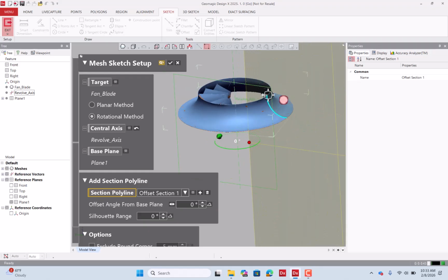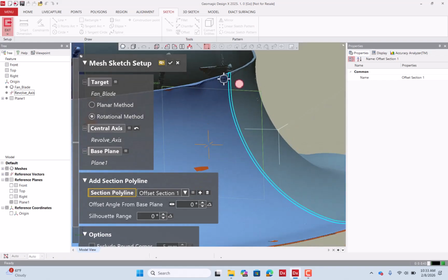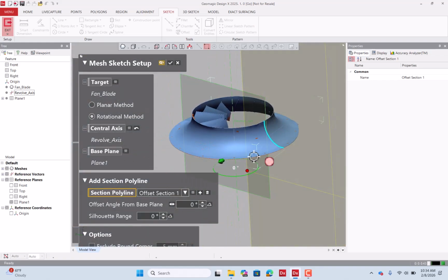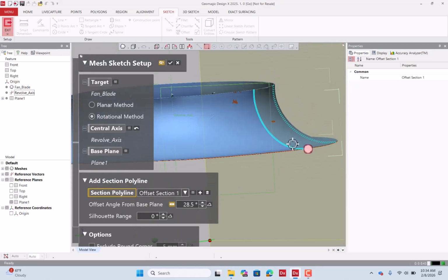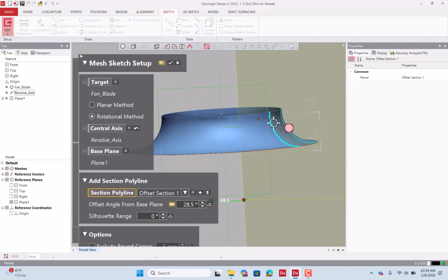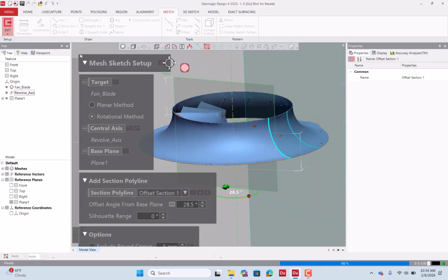If you feel this area does not have good quality scan data, you can zoom out and you'll see a thin green ring. You can move this ring to where there is very nice scan data available, say in this region, and if that preview looks good, you can say OK.